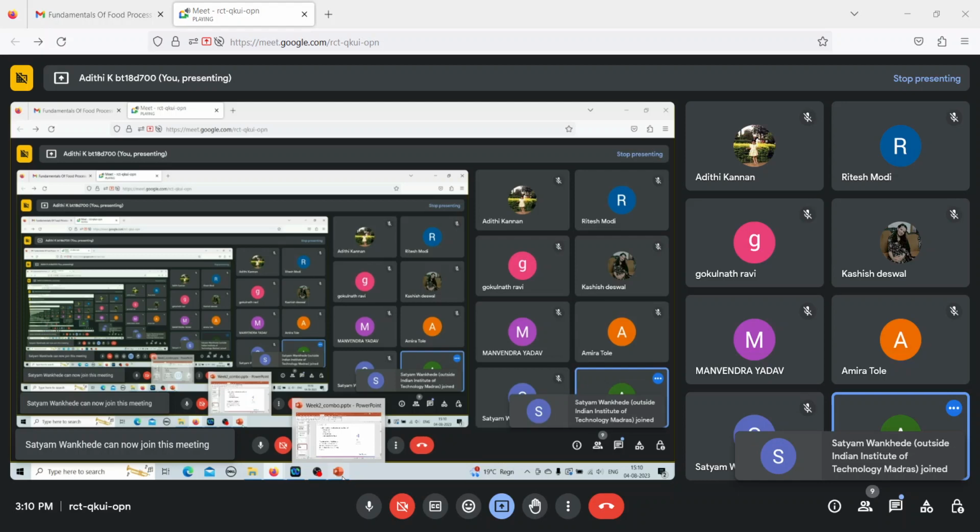In case of a cone plate viscometer, you have a plate here, and you have a cone shaped instrument here. So between the plate and the cone, you have the fluid, and this angle is actually very minute. The angle between the cone and the plate is very minute, and in that minute region you will fill the fluid whose viscosity you want to measure, and you will keep rotating the cone, and based on different forces that act on the fluid, whose description is in the lecture videos. You guys can go and look into those descriptions and the derivation. If you guys have any doubts, you can post it in the discussion forum and we'll take it up at that time.